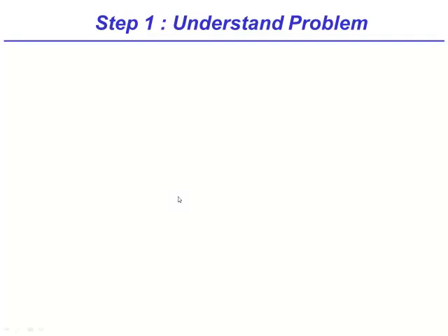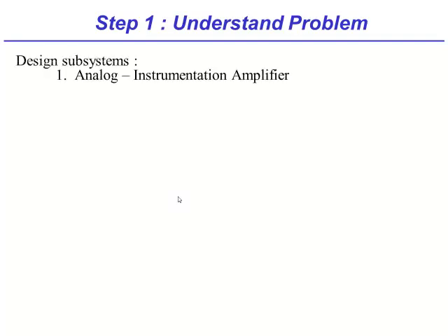Okay, we'll design the circuit by simplifying the problem into different subsystems. We first need to understand that EEG signals are on the order of tens of microvolts at around 10 to 13 hertz, at least the signals we're interested in looking at. Hence, there are three main subsystems. The instrumentation amplifier for high gain but low CMRR, or common mode rejection ratio. Recall your instrumentation amplifier lab.